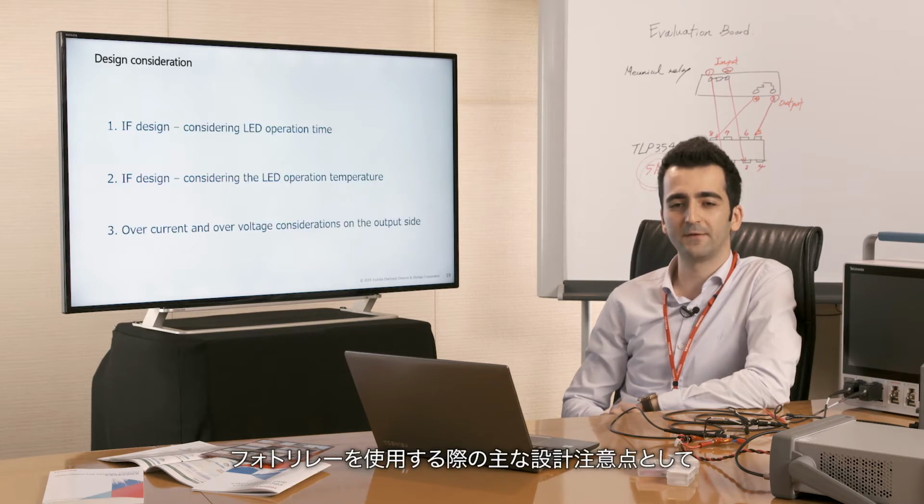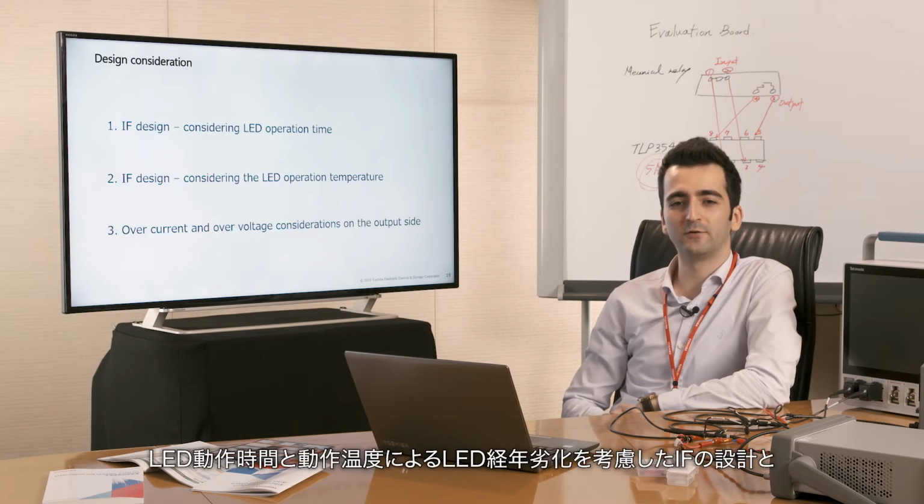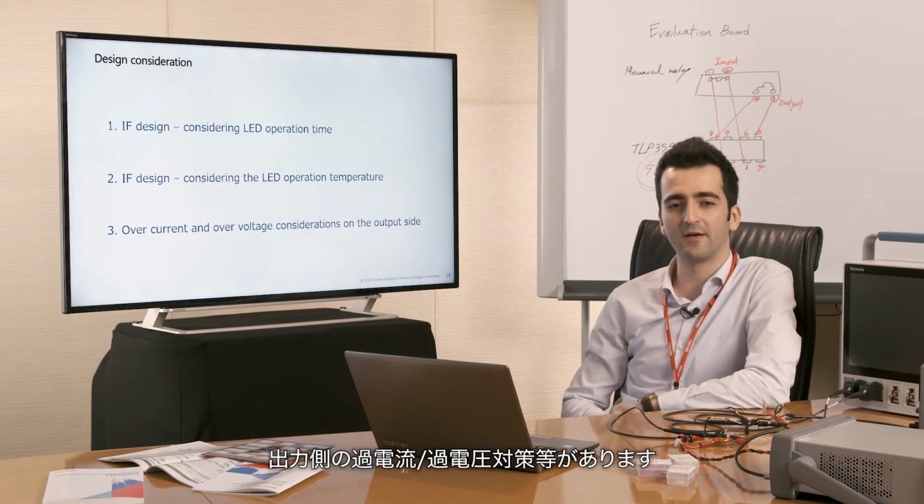When you decide to use a photorelay, first you have to pay attention to the IF design. Consider the LED operation time and operation temperature. And next, overcurrent and overvoltage considerations on the output side.